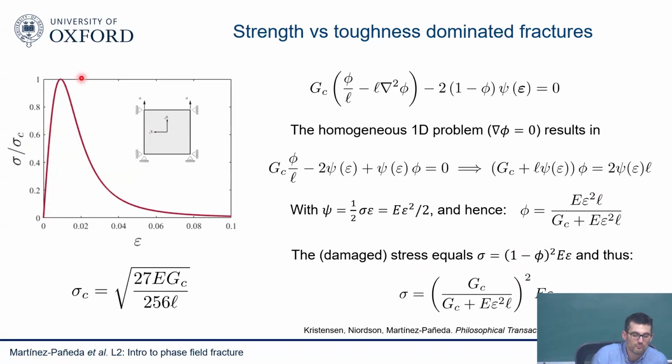Those of you familiar with cohesive zone models or some of these damage models will also recall seeing something like this. It's kind of a traction separation law. Your stress increases almost linearly. Here you start seeing some nonlinear phenomena. Eventually you reach a strength, and then you get some sort of softening degradation until you get a complete failure. This is the idea. So it's kind of a traction separation law in a cohesive zone model. At the end of the day, if you think of a cohesive zone model, it's a very similar idea, right?